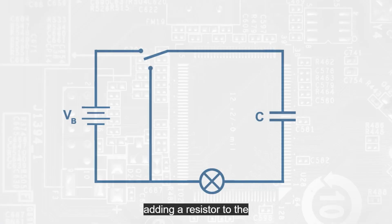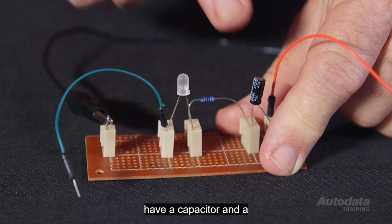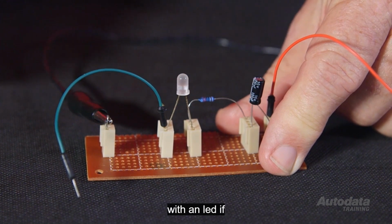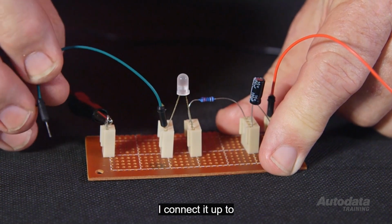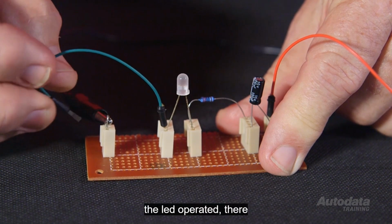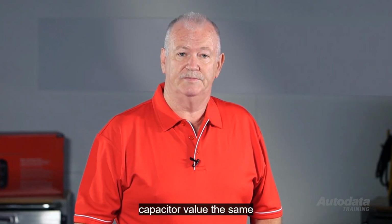Adding a resistor to the capacitor gives us a resistor-capacitor, or RC, circuit. These can be used for time delay. I have a capacitor and a resistor connected up in series with an LED. If I connect it up to the power supply, the LED operated. There wasn't much of a delay. The delay period can be altered by changing the capacitor value.